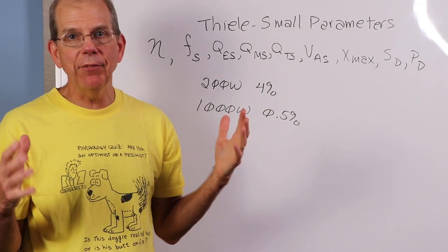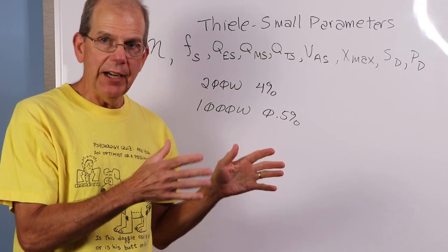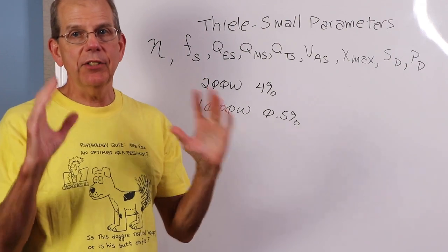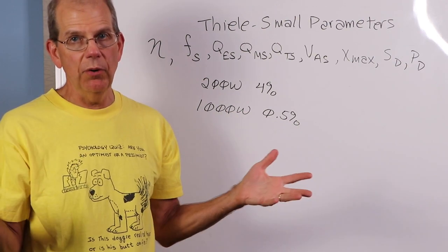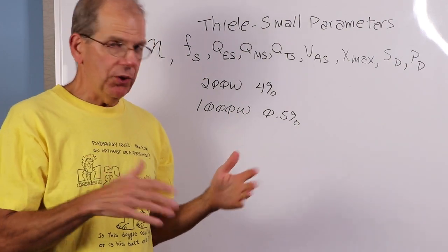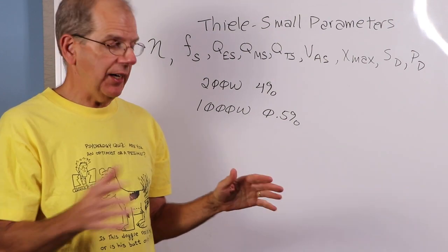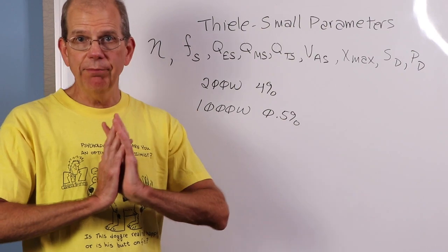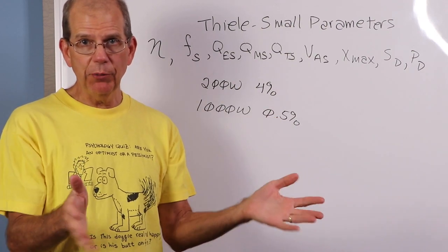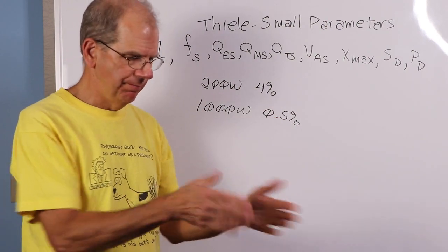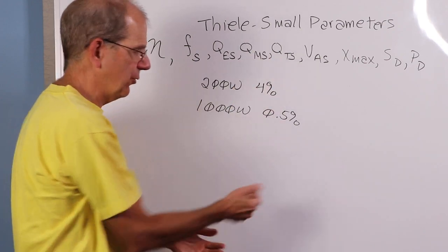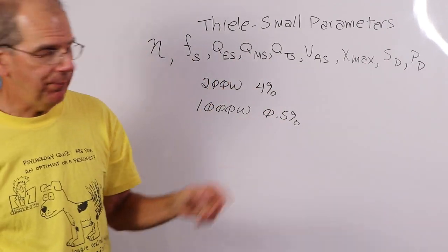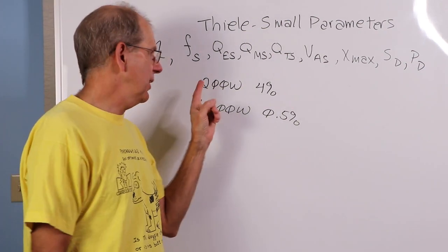The highest I've ever seen for that kind of loudspeaker is 7%, and that was actually a transducer designed to be horn loaded. But you're not going to see 25%. You're not going to see anything that high unless it's a system that's horn loaded. If it's a direct radiating system, no, these are the sorts of numbers you're going to see for efficiencies.